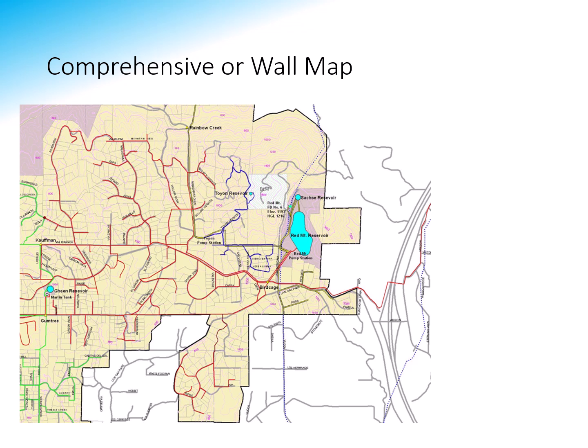Everything in red here is for this pressure zone coming off of this reservoir. You've got this blue in here, and a lot of times you've got another reservoir right here, which is probably feeding that zone. You could have other ones in here if you have pressure regulators, breaking it down. I know at VID we've got a bunch of different zones, and so our map has a bunch of different colors.